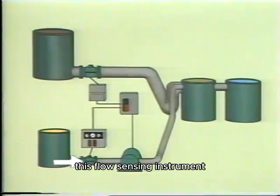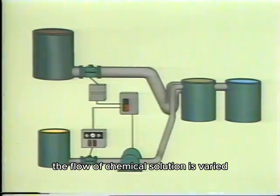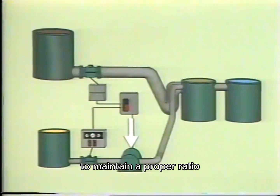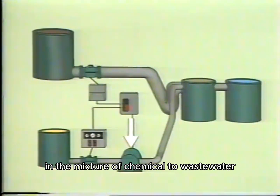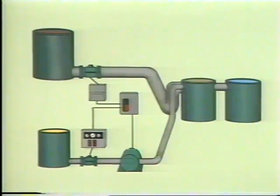This flow sensing instrument monitors the flow of chemical solution to the mixing tank. The flow of chemical solution is varied by changing the speed of the pump to maintain a proper ratio in the mixture of chemical to wastewater. This flow of chemical solution can be referred to as the dependent flow.